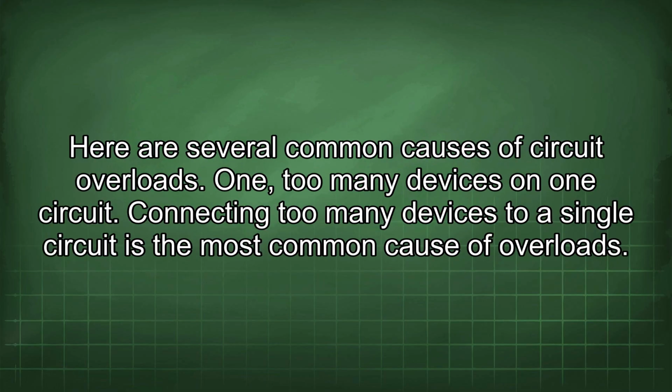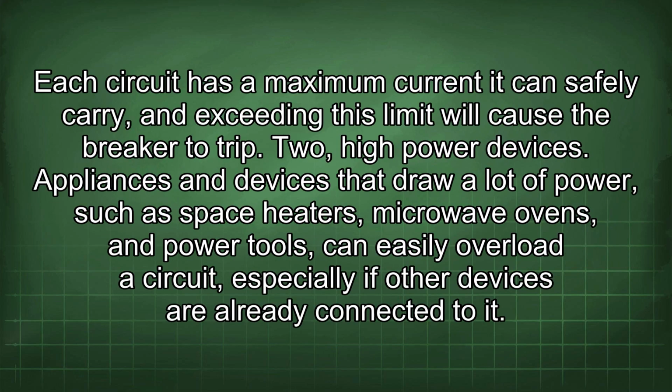Here are several common causes of circuit overloads. 1. Too many devices on one circuit. Connecting too many devices to a single circuit is the most common cause of overloads. Each circuit has a maximum current it can safely carry, and exceeding this limit will cause the breaker to trip. 2. High power devices.